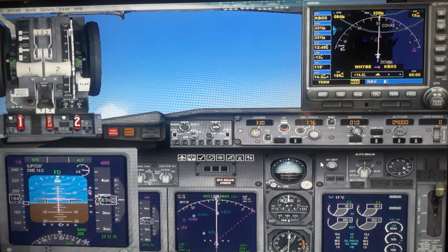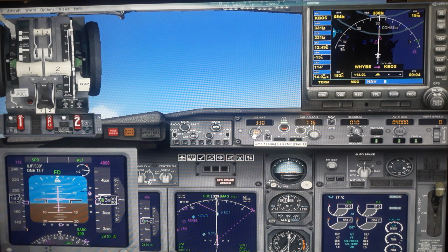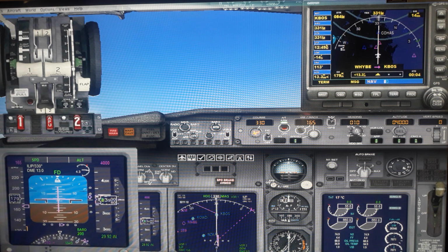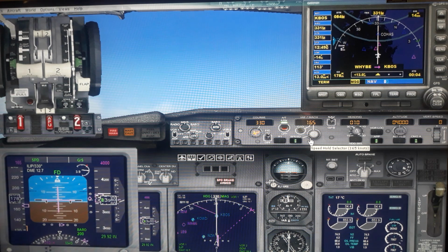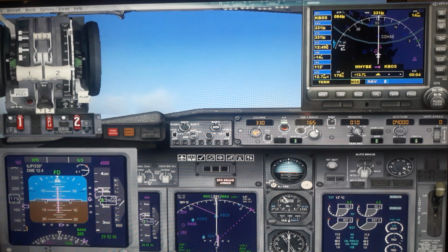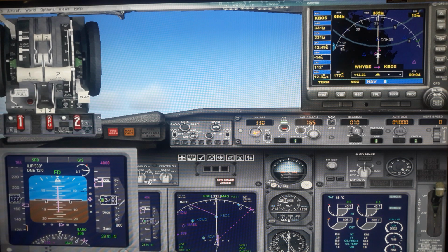Okay, now we are 14 miles to the runway, 176. Flap is set here. I'll reduce the speed to 165. And actually I'm doing it a little earlier than required. You don't do that normally because you want to save fuel, but I am doing it a little earlier so we are free. I'll reduce the engine noise a little more so we can really see.